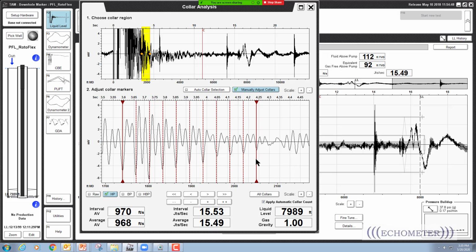It's very accurate. Once you get more and more CO2 in the gas, then the CO2 gas doesn't act like a hydrocarbon gas, and so it's not as close. So there's more and more difference between the gas gravity from the software when you compare it to gas composition. I'd say more than 30%.